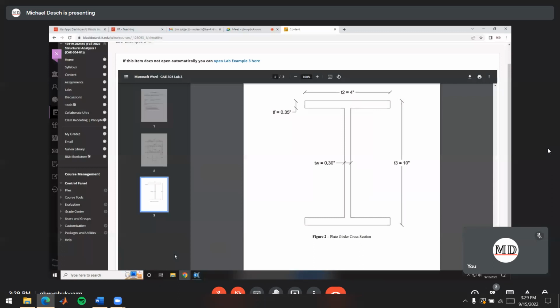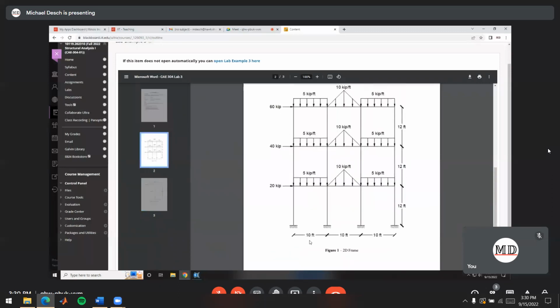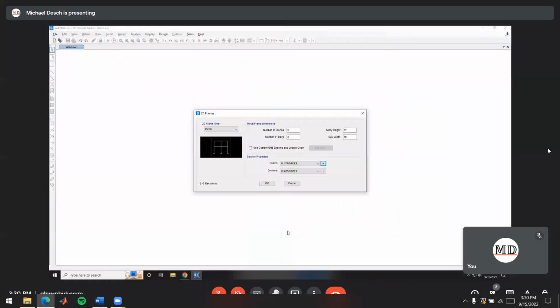If you look at the model that we want to be making today, we want these to be fixed supports. By default, this gives us pin supports if we keep reactions on. Now, I usually uncheck this so that I remember to put in fixed supports, or I'll forget and they'll stay pinned and it'll give us different numbers. So I'll uncheck that and then we're ready to go.